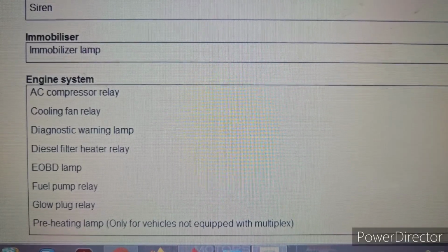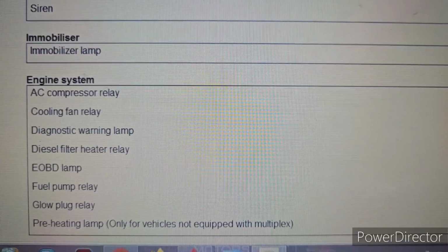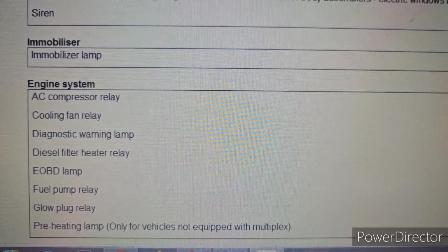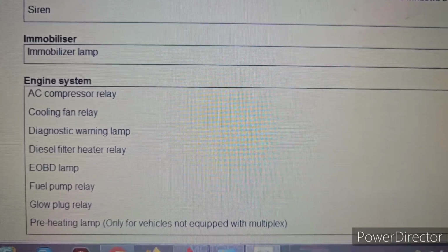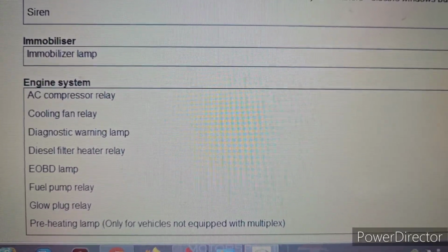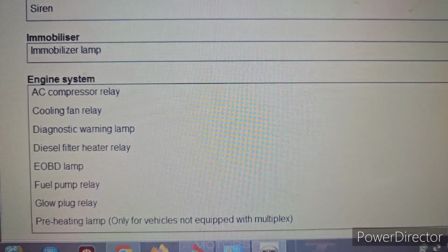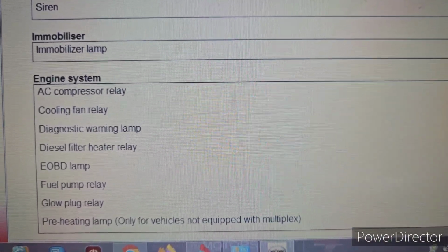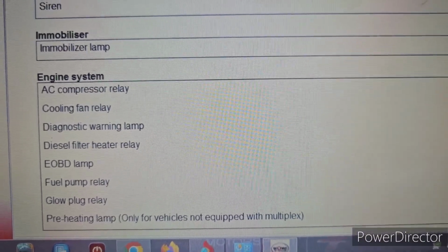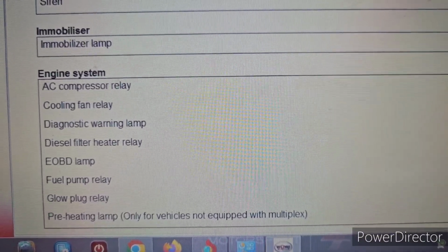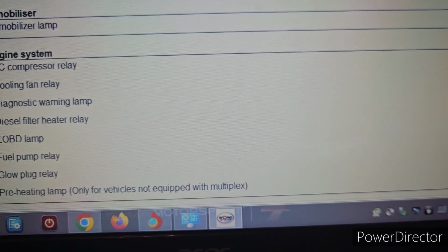So what you do is you put your fuel gauge, and you have these tools that activate the injector in a certain time, and you will find whether the injector is working properly. So you need to build a pressure on the fuel system. So you can use this feature, guys.